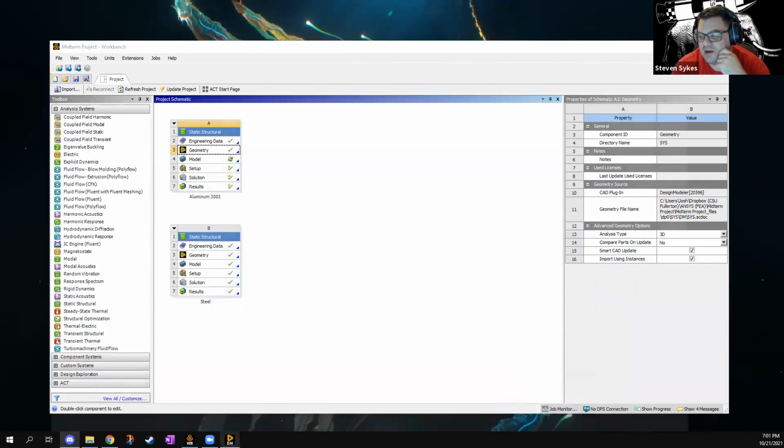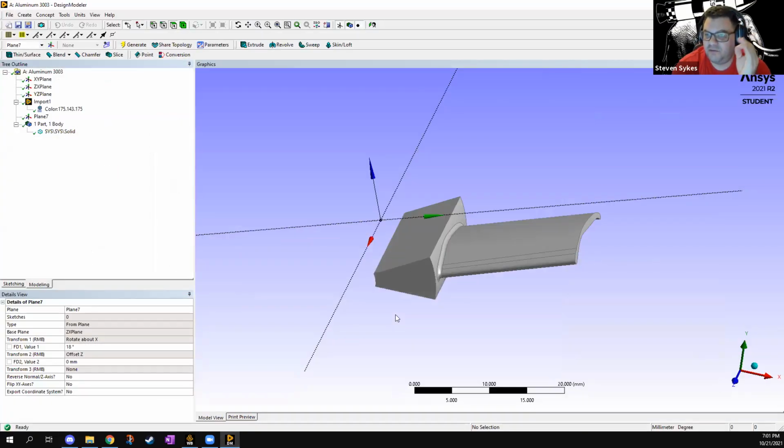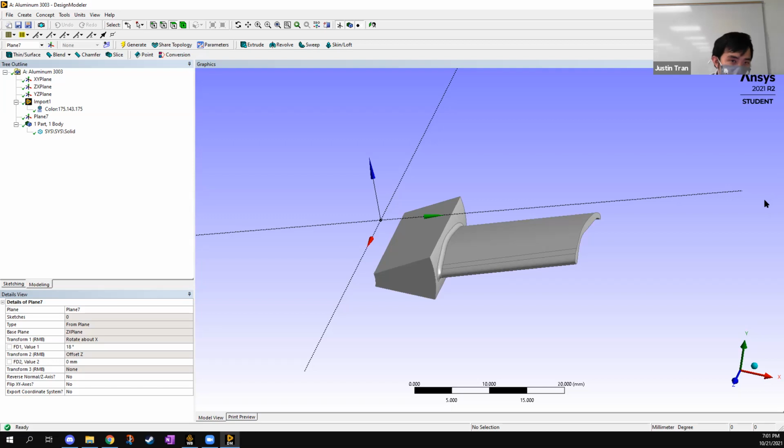Okay. And then I don't need to simulate any kind of fluid flow over it in order to get that. It's just a straight pressure for that scenario. Yes. Okay. So it'll be an approximation, and one thing you can do is compute what you expect to be an overall lift coefficient for this, and then translate that into a net force in the vertical direction. In the vertical, that's how I read it. Yeah.